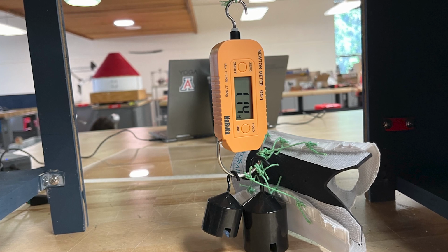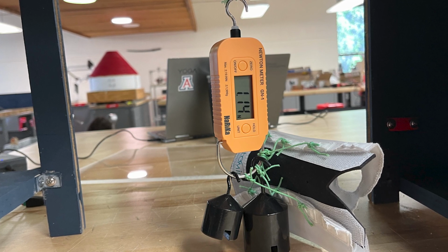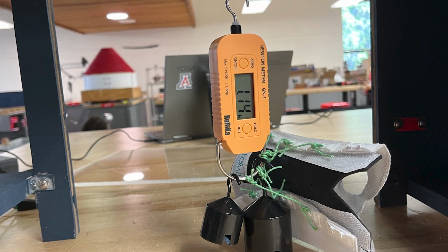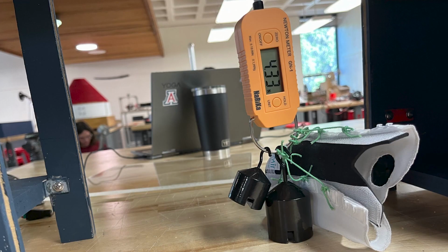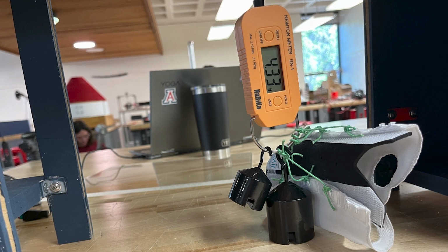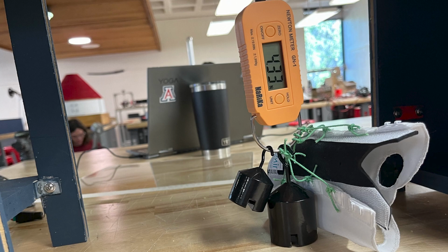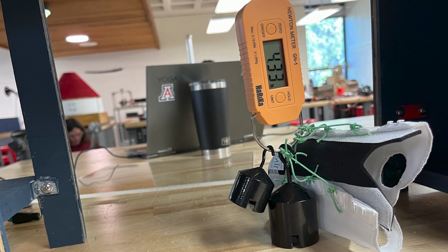We used the gravitational simulation model to determine what necessary net force value we would need to observe on the force sensor, as well as what the margin of error was for a 700-gram rat on Earth, Mars, and the Moon. Following that, we ran a gravitational simulation acceptance test and were able to simulate all gravitational forces within the margin of error determined by the analysis.